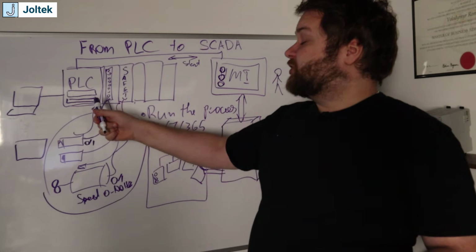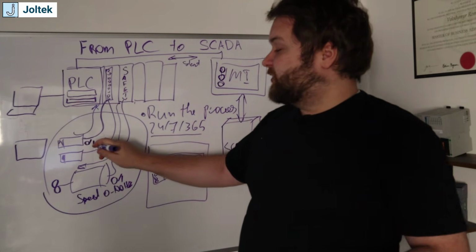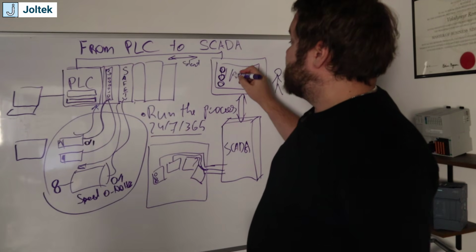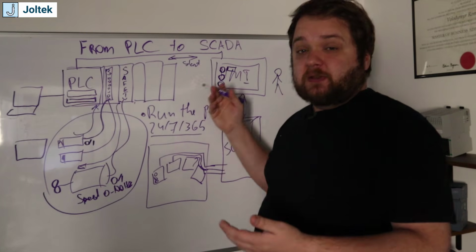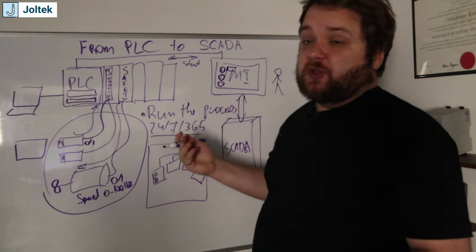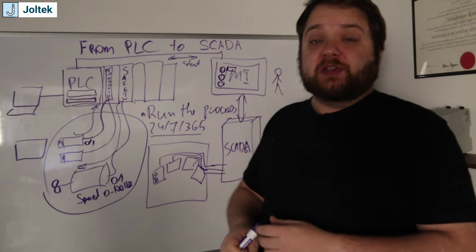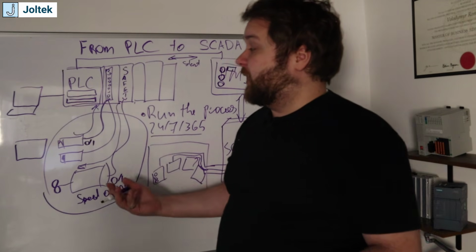And so those registers can then be presented on the HMI. So for example, we can have the sensor that is activated that will set off maybe some kind of a message here, right? So box present, and that will be displayed on the HMI. As I've mentioned, that is raw data. That is the simplest form of information that you can collect and send to the plant floor.